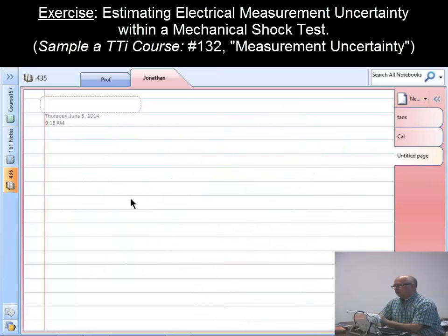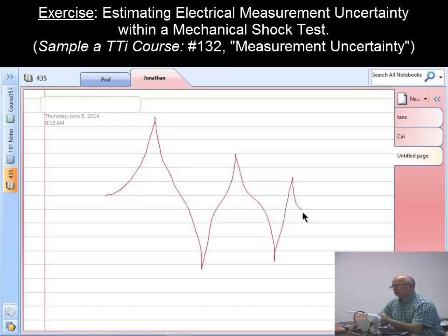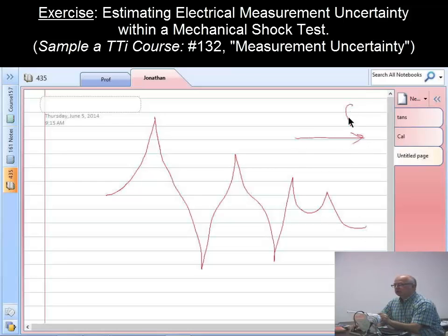With vibration testing, if you test a very, very resonant structure, like a bell, for example, and you look at its frequency response characteristics, they'll have a very sharp resonance because there's very little damping, it's bell-like. There'll also be some very, very sharp anti-resonances, we call them. There may be saddle points depending on what we're measuring. And so this is frequency against some measure, maybe a transfer function, maybe acceleration, some measure of level of vibration.